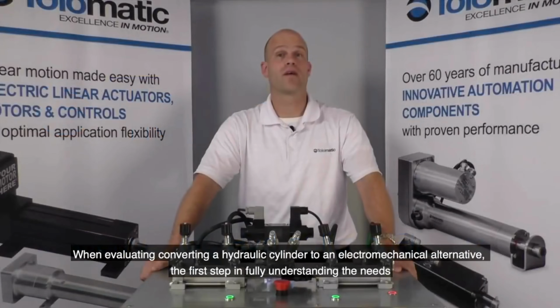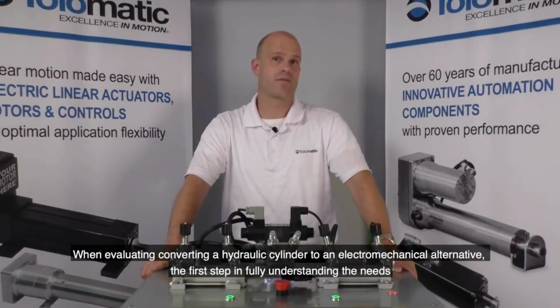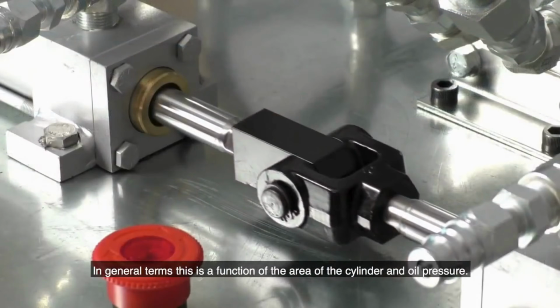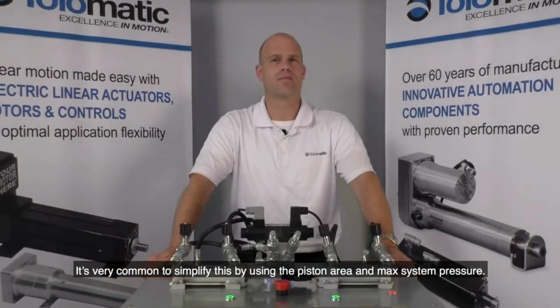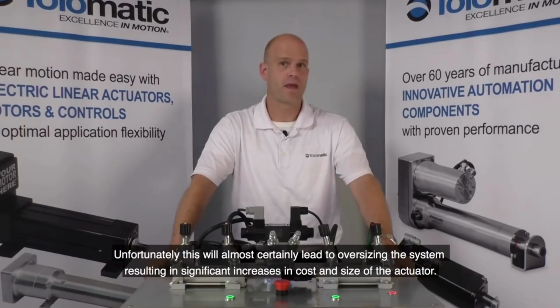When evaluating converting a hydraulic cylinder to an electromechanical alternative, the first step in fully understanding the needs of an equivalent solution is to understand the amount of work that is being done. In general terms, this is a function of the area of the cylinder and oil pressure. It is very common to simplify this by using the piston area and maximum system pressure.